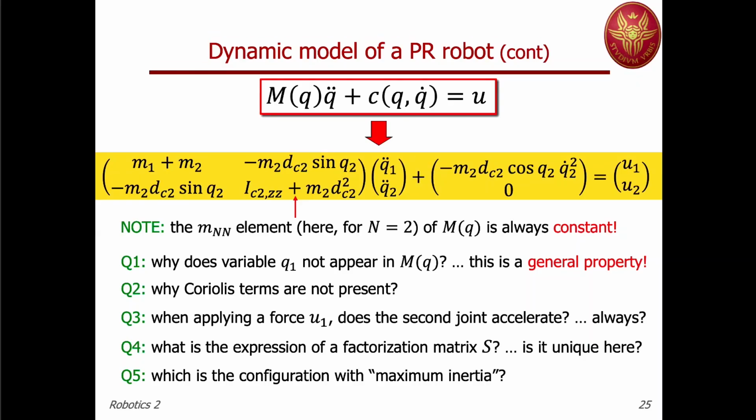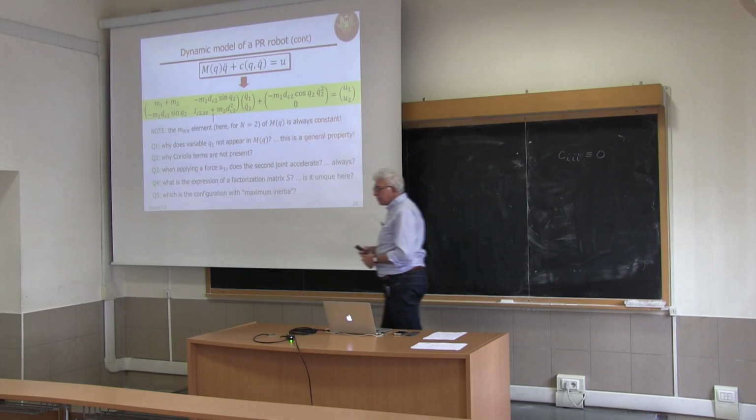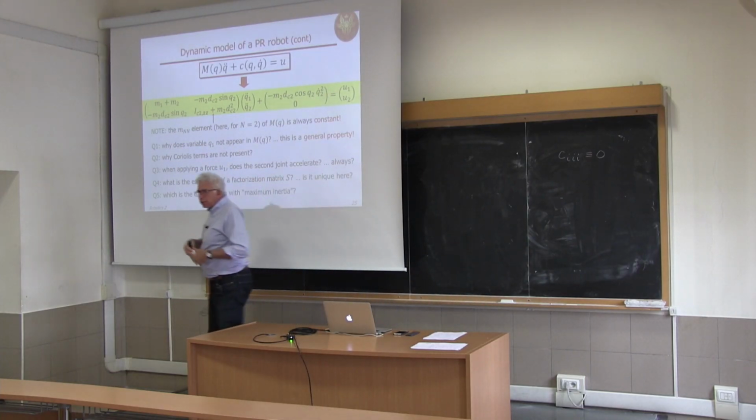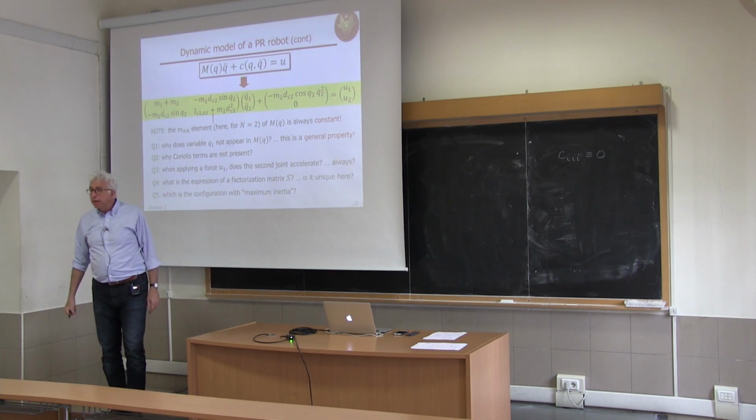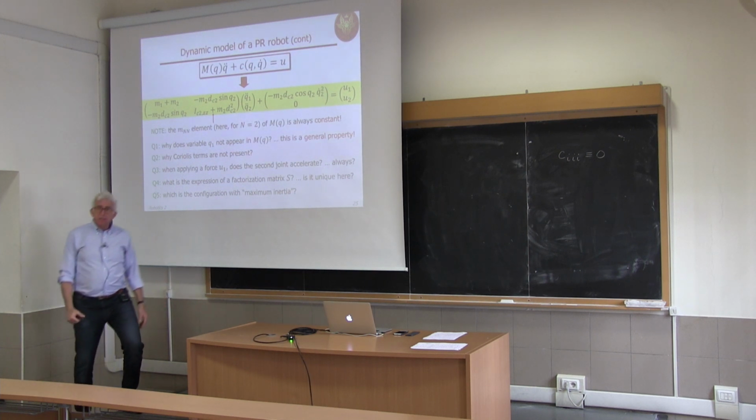The last question is the most intriguing one. We have mentioned that, for instance, at the kinematic level, we have a manipulability index for a robot, which corresponds to the fact that in a certain configuration, we have a better transformation of joint velocity into end effector velocity. And of course, if we have redundancy for a given position of the end effector, we may find the best configuration that maximizes manipulability, or maximizes manipulability in a certain direction. Are there similar concepts at the dynamic level?